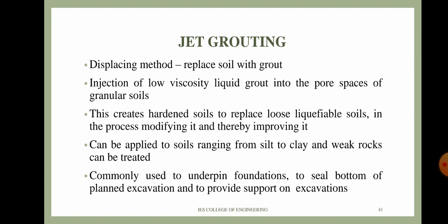And there are mainly different types of grouting, and we are now discussing some of the common and important ones. Jet grouting falls under this category. Jet grouting is a displacing method. That is, it replaces the soil with injected grout.